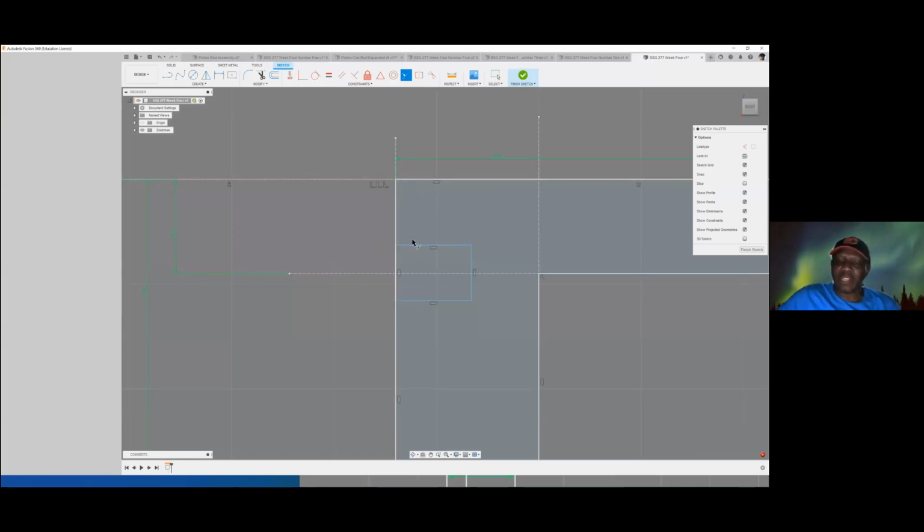So this is there. So the next thing for you to do is to come and now put the dimension on this one. So you have to know what distance you want this to be, what is the width, and what is the length. And now the length, you can create a dimension if you want a sketch dimension, and then you create this, and let us say you want this to be 3.8.